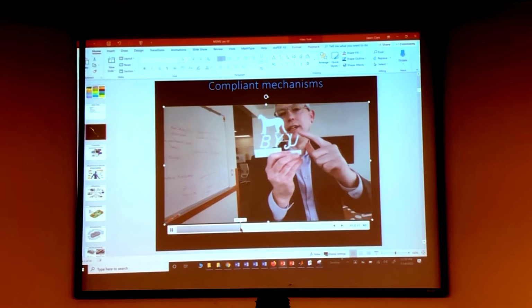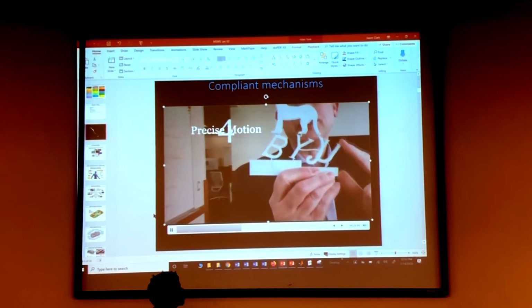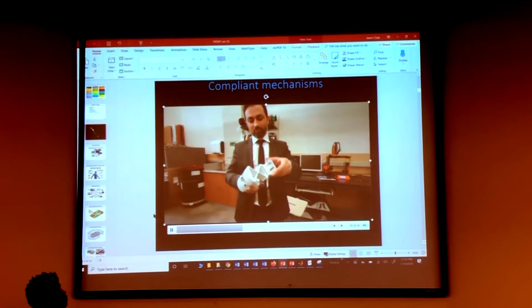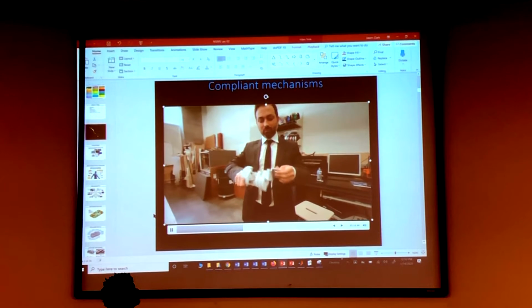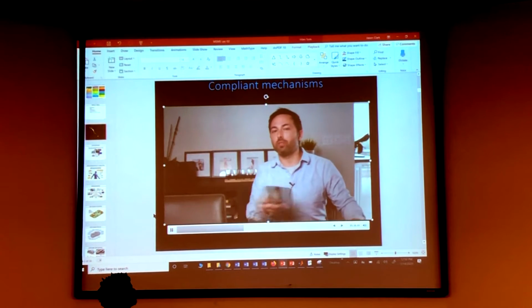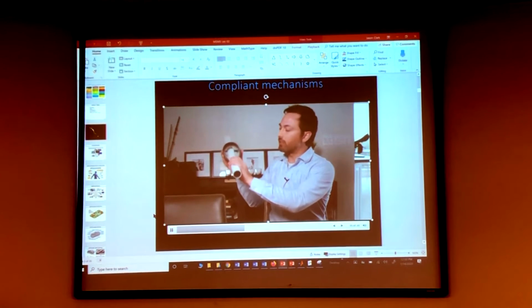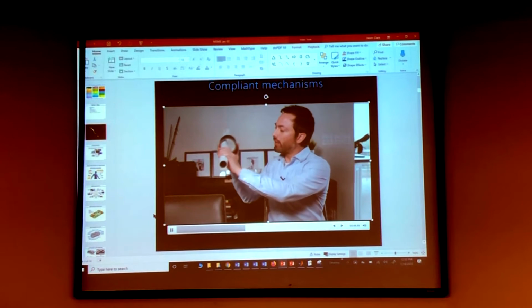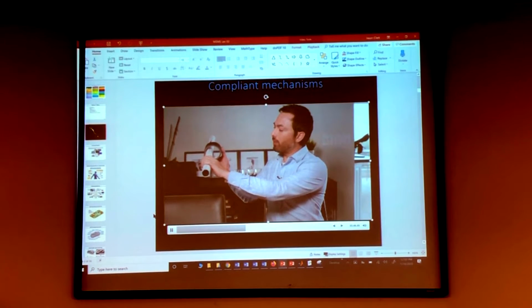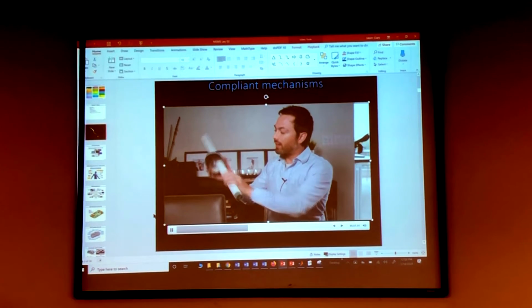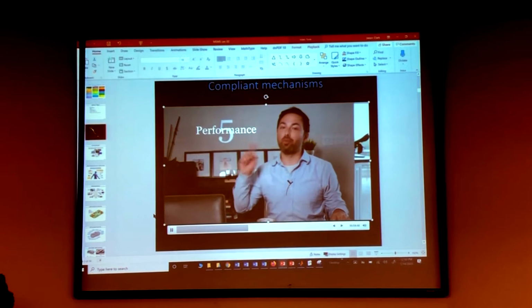Demonstrate that compliant mechanisms are capable of producing very precise motion, which I personally found pretty counterintuitive because these objects are made up of flexible parts. But maybe that shouldn't be surprising, because compliant mechanisms don't suffer from backlash, for one thing. Backlash occurs when you have a hinge, which is basically just a pin in a hole, and it's moving in one direction. And now, if at some point the motion reverses, it doesn't happen instantaneously because there's some give in the hinge. This also causes wear and requires lubricant, and that is why compliant mechanisms have better performance than their traditional counterparts.